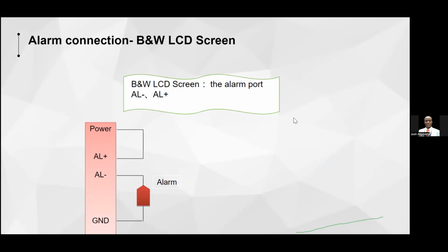So, international standards of access control deployments: for every access control you deploy, whether standalone or control panel, you are supposed to have an exit button and an emergency relay. Even in your F18, F19, F22, there is a relay for an emergency exit button, or a different relay that you can use in events of fire.